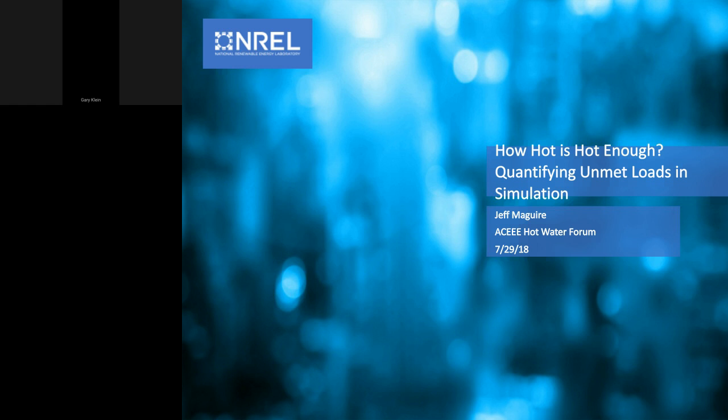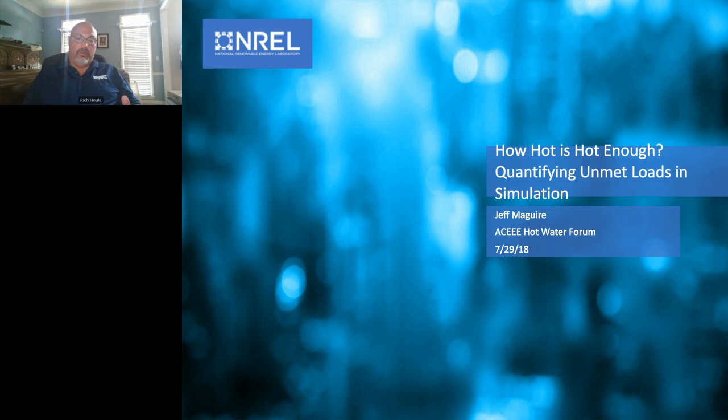Rich, have you looked at what elbows and fittings would do to the overall sizing calculations? Yeah, and that's part of the next step to designing the plumbing system, as far as determining what our pressure loss through the system is. That's going to have an impact on obviously how we size our systems. It may change what available pressure we need to have, so it may change the incoming pressure requirements, PRV settings. But yes, when we get into the overall system design, as Emily had indicated, when we look at right sizing our plumbing systems, pressure loss becomes a much, much bigger topic of discussion.